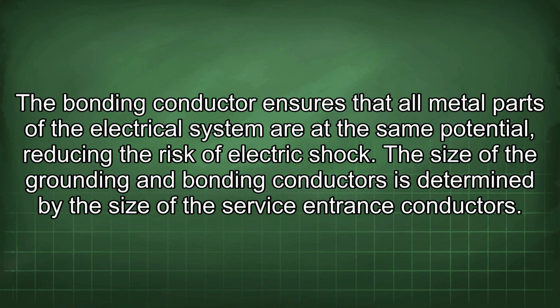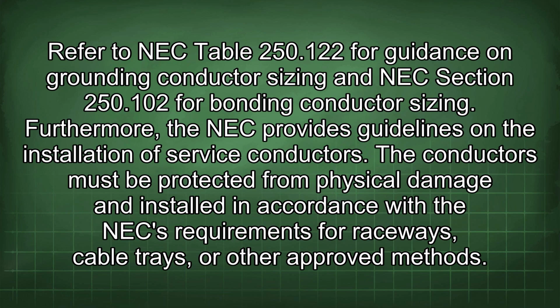The size of the grounding and bonding conductors is determined by the size of the service entrance conductors. Refer to NEC Table 250.122 for guidance on grounding conductor sizing and NEC Section 250.102 for bonding conductor sizing.